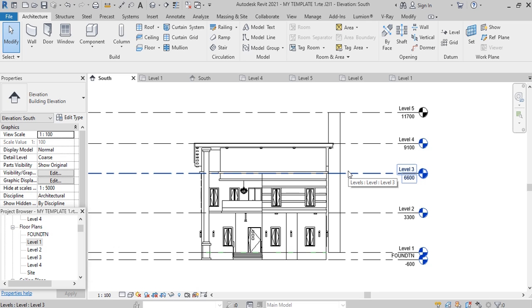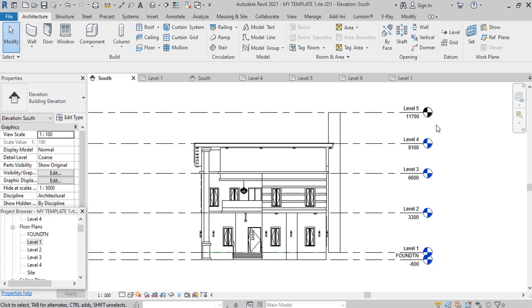Now say for instance I want to create something, maybe just to create a cap at the top of this wall. There is no way I can do that except I start creating it at this level and start calculating the height of the wall and offsetting it to that point, but it's a long process. What I ordinarily have to do is to go to this level and create whatever I want to create. But now I can't do that because there is no level for this. This is just a reference line, okay?